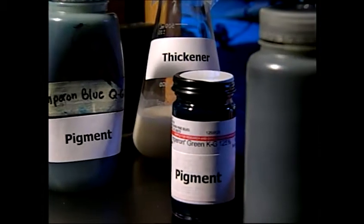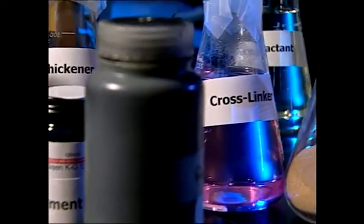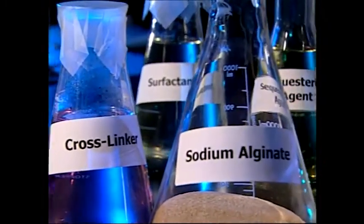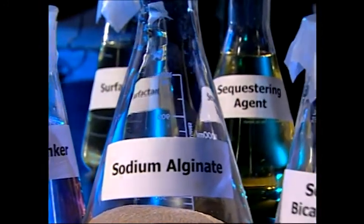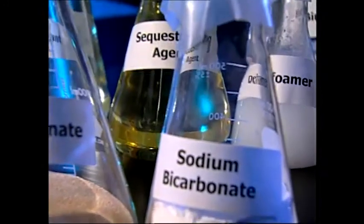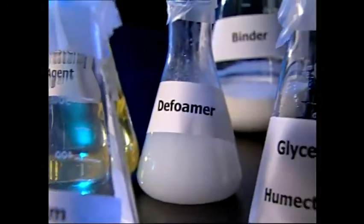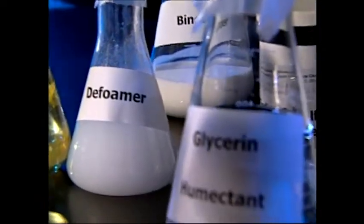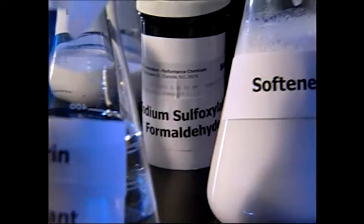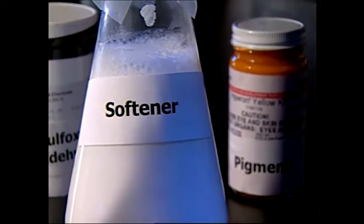The specifics of the print paste formulation depend on the fiber content of the fabric, the colorant system used, and to some extent, the type of printing machine employed. The typical ingredients found in most paste formulations include dyes or pigments, thickeners, sequestering agents, dispersing or suspending agents, known as surfactants, water-retaining agents, known as humectants, defoamers, catalysts, and hand modifiers.